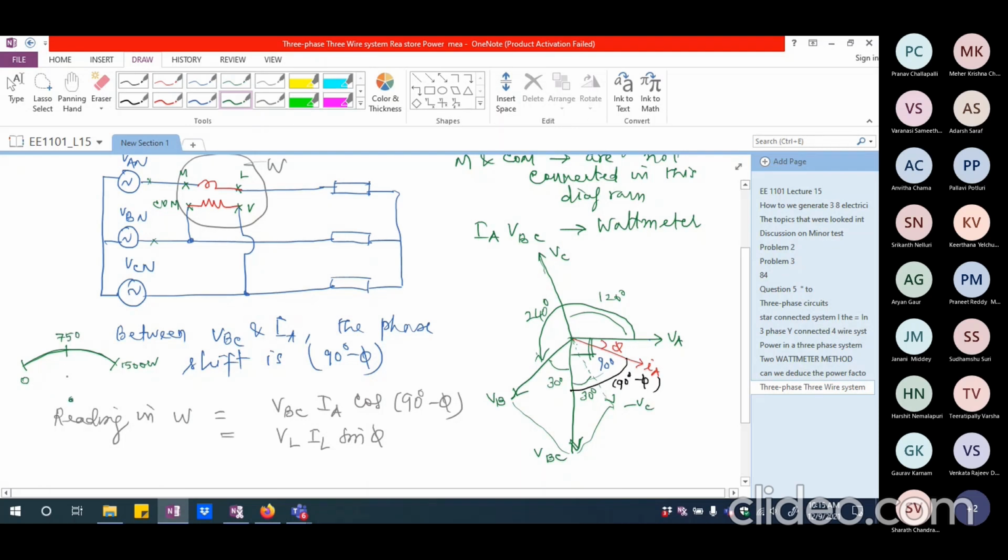So if this is the pointer, the pointer will essentially indicate somewhere here, or it may go within this 1500 watt range. Now, if it is going to show minus, then you would see that the wattmeter reading will be kicking back. That is, it will actually go beneath 0. So we will call this as wattmeter reading, wattmeter pointer is kicking back.